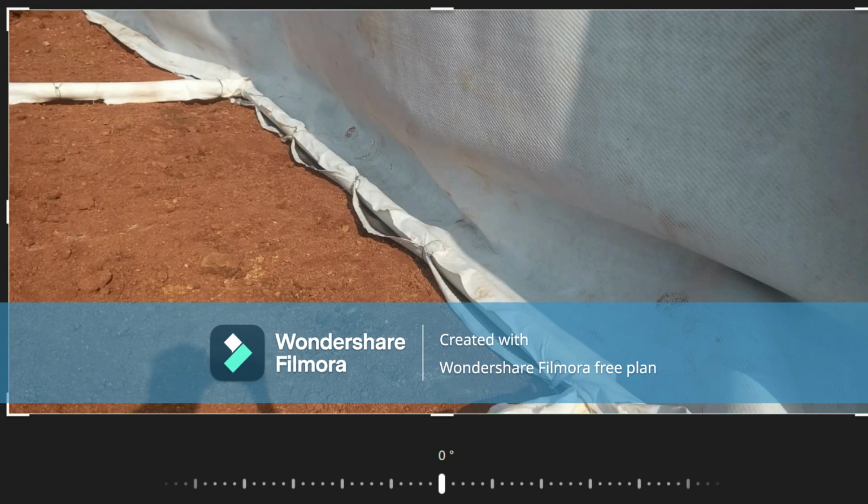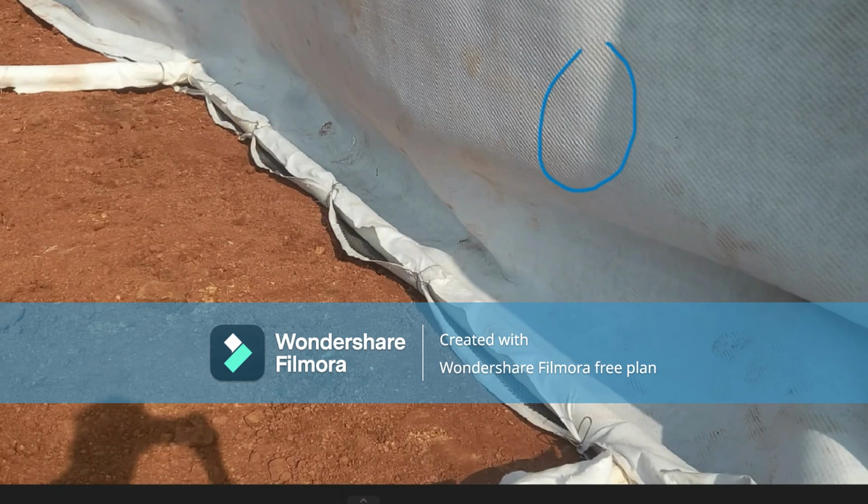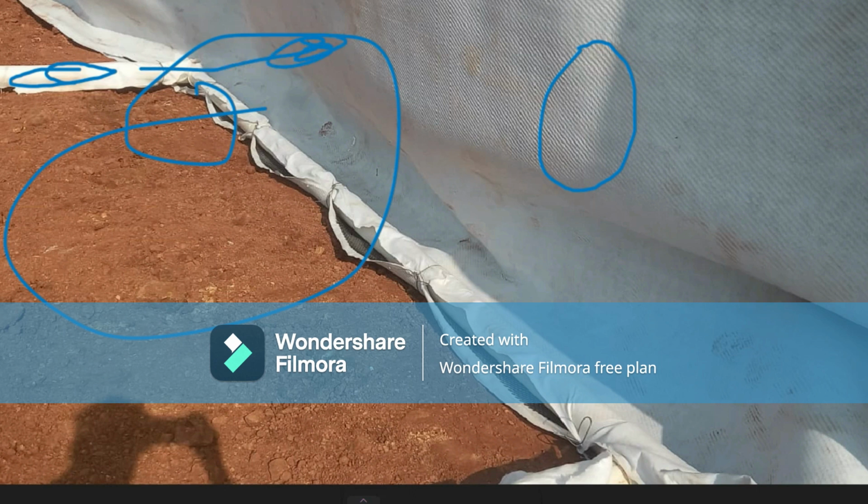Yes, this is a geocomposite or non-woven geotextile along the vertical wall of the existing soil. Then the second one will be constructed, and this is the PVC pipe wrapped with the non-woven geotextile and connected behind the geotextile, and the water behind the soil will pass through this PVC pipe to the drain. Here we will construct the second one.